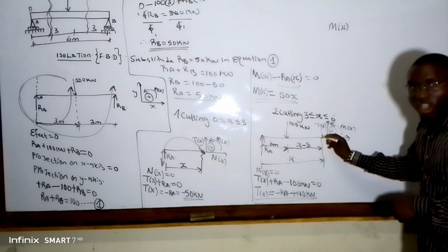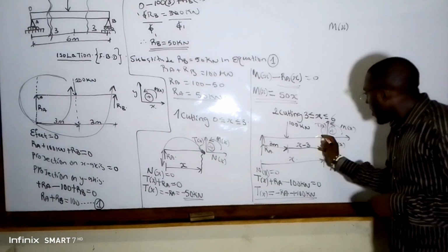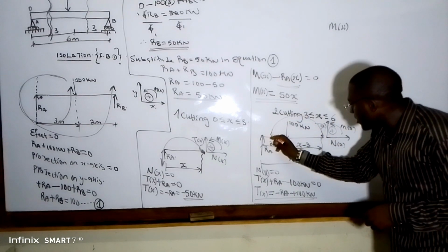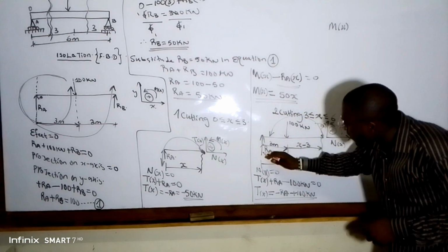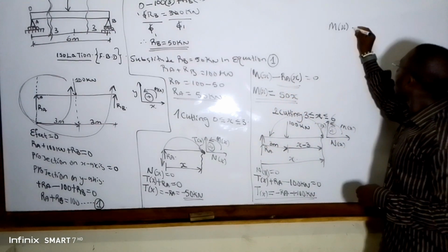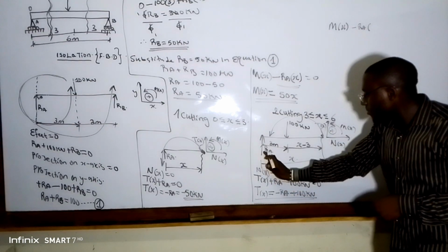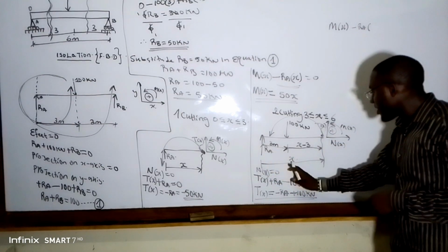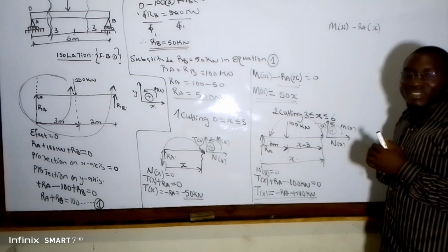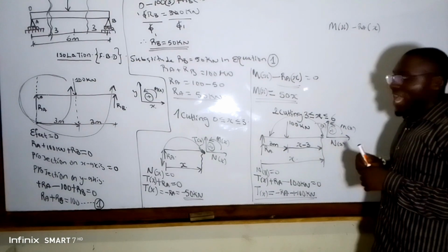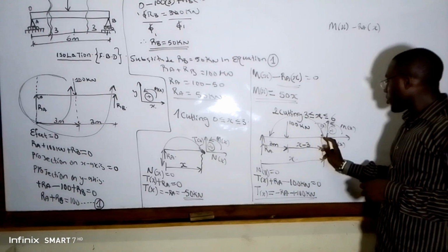this is where our center of moment is. Now, our moment is rotating like this. This force is coming down while our R_A is going up. So our R_A receives a negative sign, times the perpendicular distance from R_A to our center of moment, which is x. Guys, is it okay? I believe it's okay. So let's take the moment of 100 kilonewton about this point.